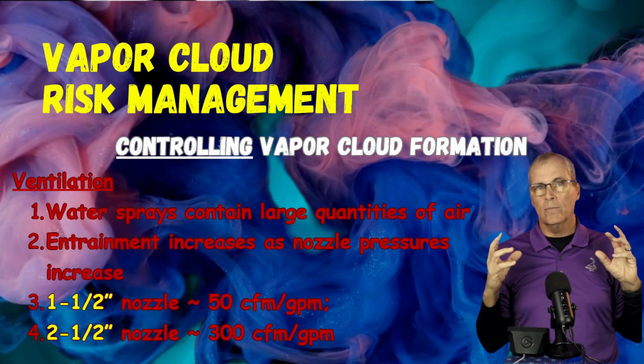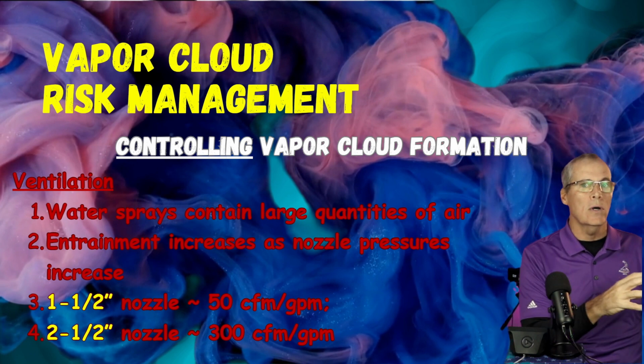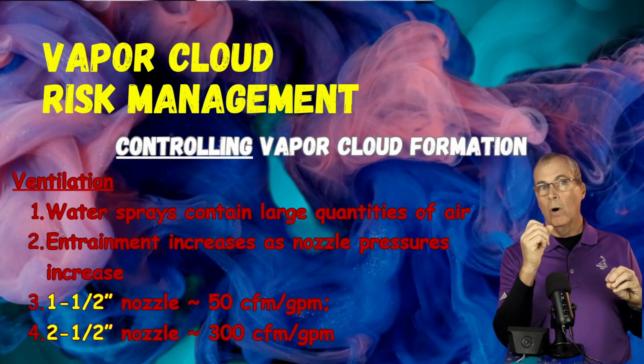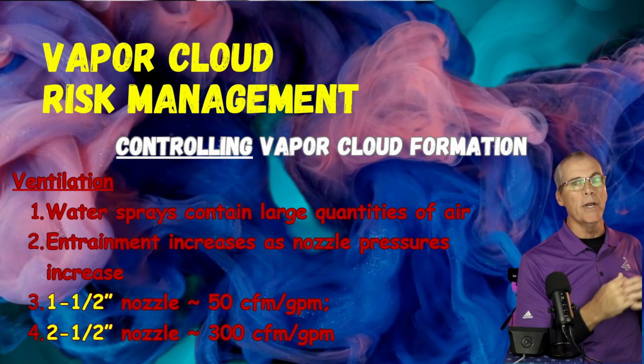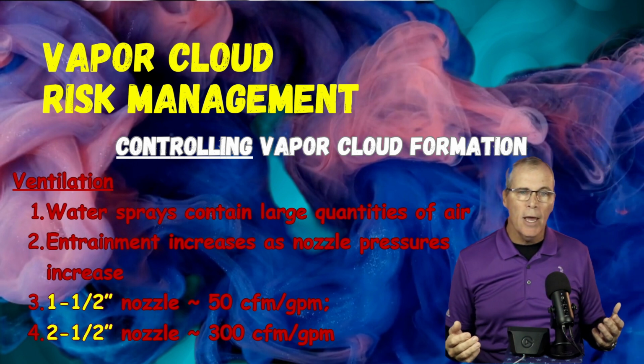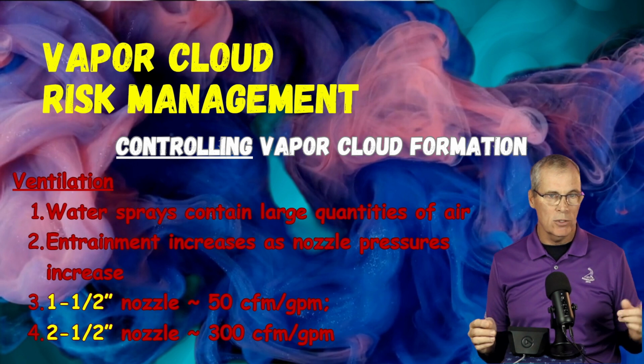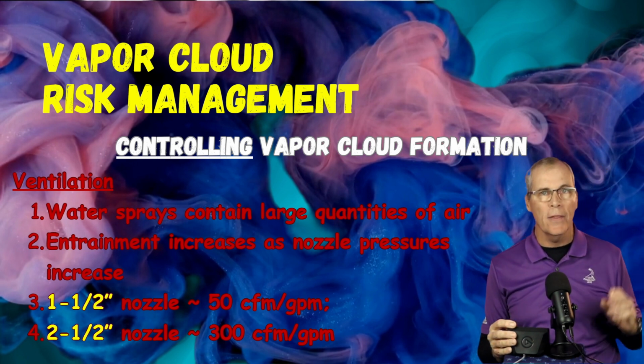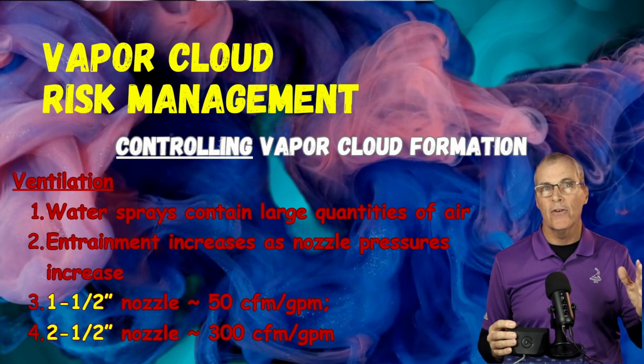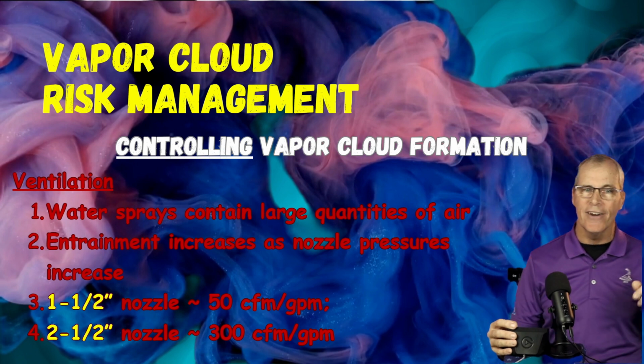If you have a whole lot of small droplets, you move a lot of air. If you have one big droplet, you only move a little bit of air. Okay, a 1.5 inch nozzle is going to move about 50 CFM per GPM. So keep that in mind. We'll do the rest of the math. I know you engineers are all trying to figure out how many CFM you get out of a hose line. We'll get there.